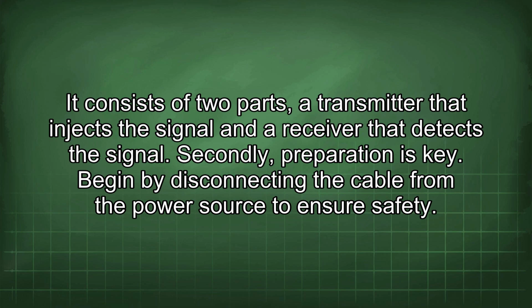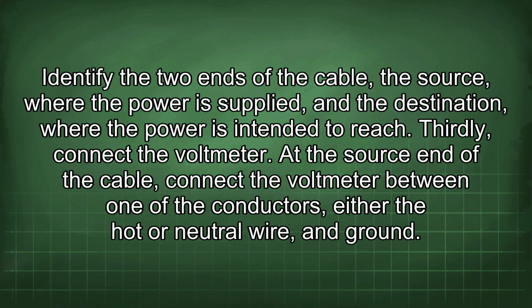Secondly, preparation is key. Begin by disconnecting the cable from the power source to ensure safety. Identify the two ends of the cable, the source, where the power is supplied, and the destination, where the power is intended to reach. Thirdly, connect the voltmeter.